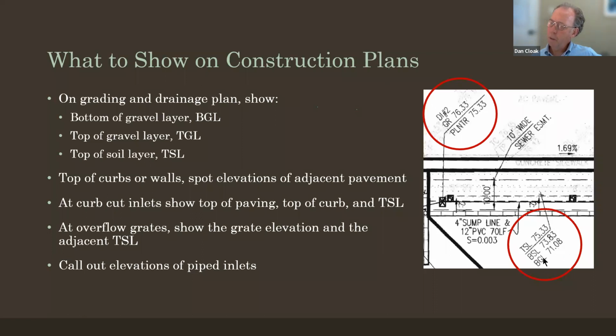But here's the top of soil, bottom of the soil layer and the bottom of the gravel layer called out at each point. This makes it easy, or relatively easy, to set up when a construction level is set up on the site, and the plans are spread out across the hood of the pickup truck, that the key elevation can be referenced, and that each of these can be identified about where it shows up.